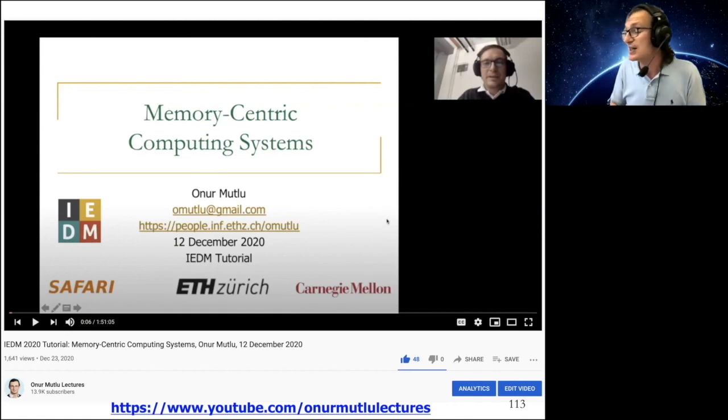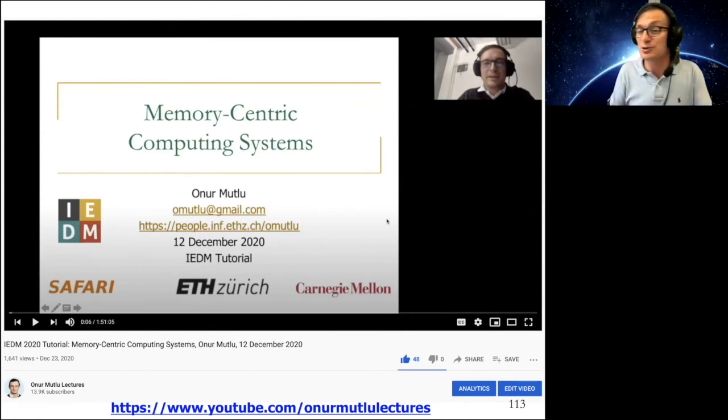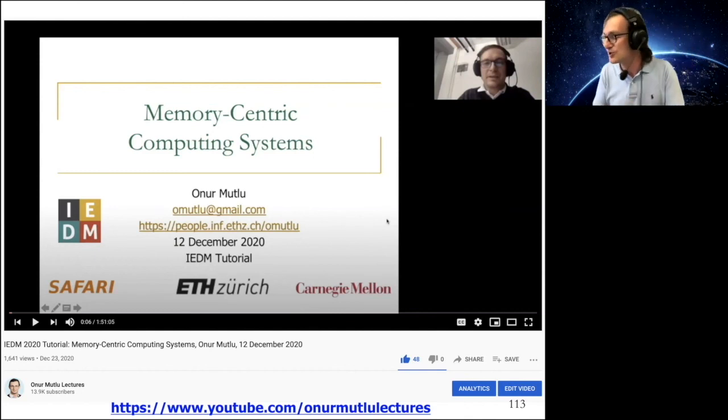Second, traditionally there has not been much error correction in DRAM because people thought DRAM was the perfect memory technology. In fact, consumer systems have no error correction. Increasingly people are adding error correction, but people are also finding that you can circumvent it to do RowHammer attacks. So DRAM is very special because of these two reasons, and as a result, you can launch RowHammer attacks.